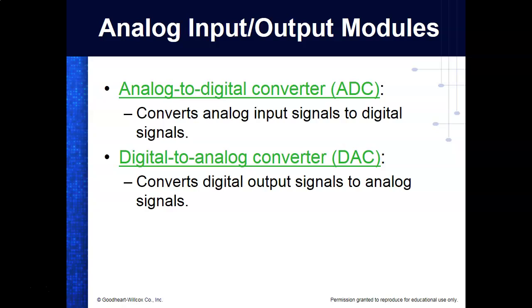The Siemens PLCs have 12-bit A/D converters on them. So that means it could convert into a number up to 4095, where the 10-bit one gives up to 1023.